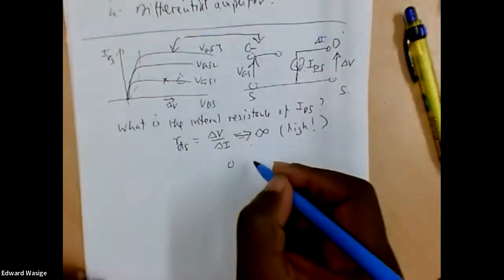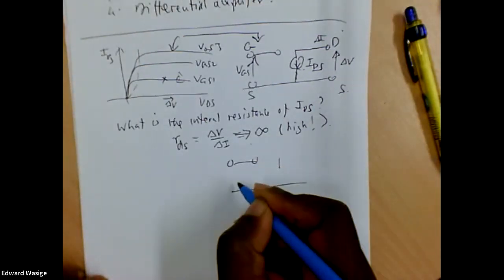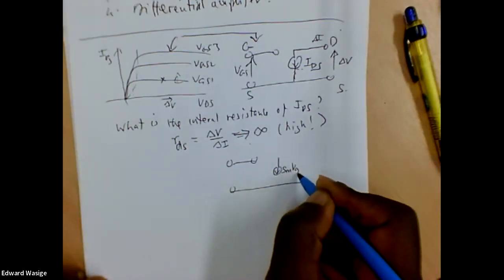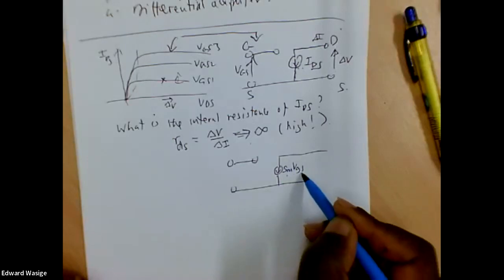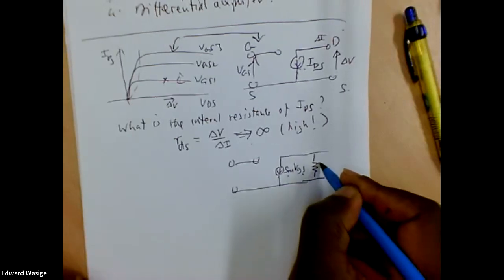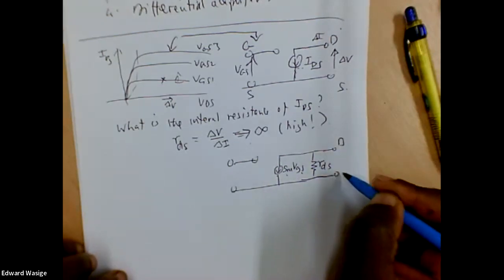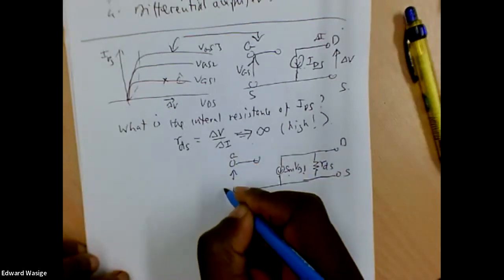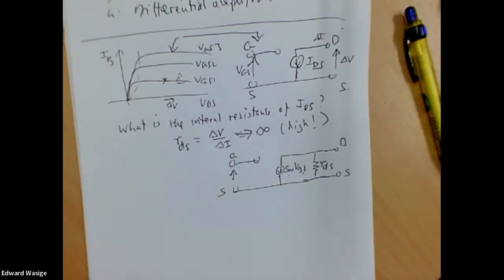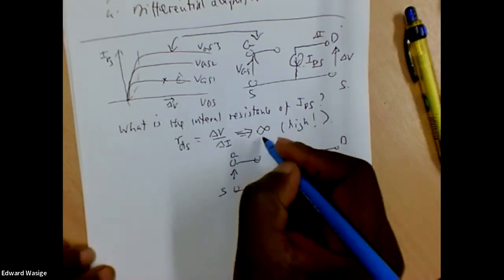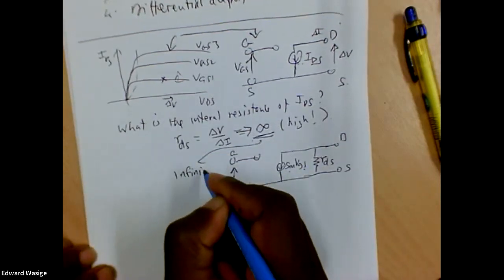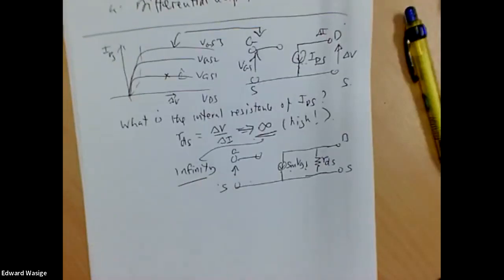So the large signal, we write it like that. We draw it like that. The small signal, as we saw last time, the current source, small signal current, we can write as transconductance times VGS. And between the drain and the source, we can have a resistance RDS, and this resistance is a large resistance. That's right, the resistance is high. It's unlimited, if you want to put it that way. Unlimited is probably not the right word, but you know that symbol. The English word for that is a very large number or infinity. It's a high resistance.